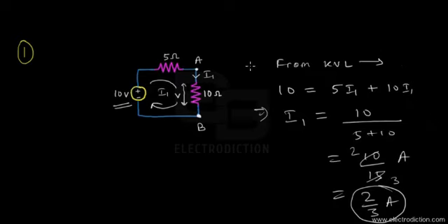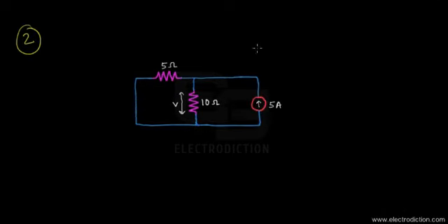From here on, we'll go forward to step number 2, where we shall be excluding this 10 volt source and including the current source, the 5 amp current source that we have on the right. Let's remodify the figure again. We've reached step 2, and we have remodified the figure once again. Since we're supposed to short voltage sources and open current sources, that's what we did in the last step, step 1. Now we have eliminated the voltage source, that's 10 volts, over here.